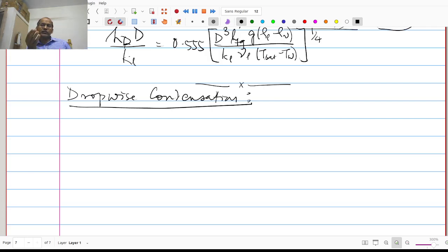So the surface tension coefficients are low, and therefore the wetting angles, the angles of contact, are very low acute angles, and therefore the liquid spreads over the surface and wets it completely, and flows along the surface as a continuous film. Whereas what can happen if the surface tension coefficients are high, or the surface is hydrophobic to the liquid in question, then the contact angles become obtuse and the liquid film may not stick to the surface.